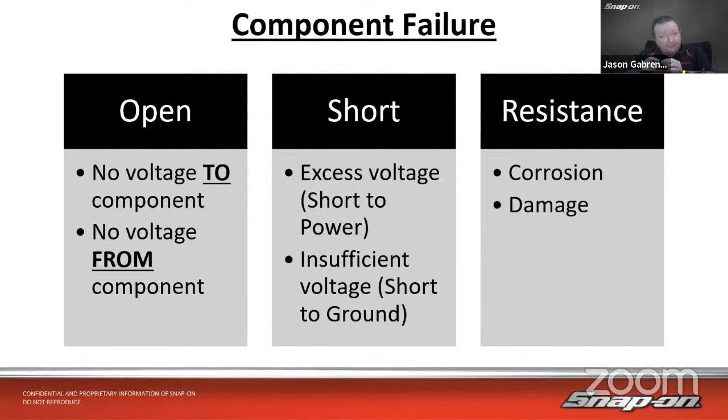If I fray a wire, even if it's not shorting right now, that could cause a resistance issue. Think about a multi-strand wire. Let's think about maybe a battery cable, right? Lots of multi-strands. If I were to take my ohm meter and put it on either end of that multi-stranded battery cable, I'm probably going to get 0 ohms or pretty darn close, right? I'm going to have continuity. Now, let's say I take out all but one single tiny strand of that multi-stranded wire and do the same thing, put my ohm meter on either side. Probably still going to get 0 ohms, no excessive resistance, continuity.